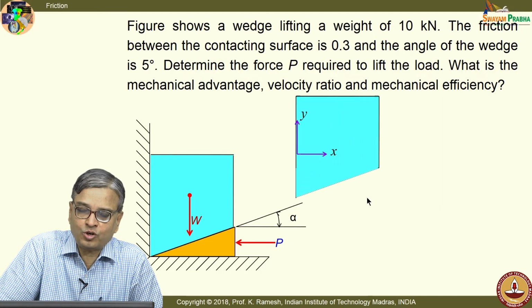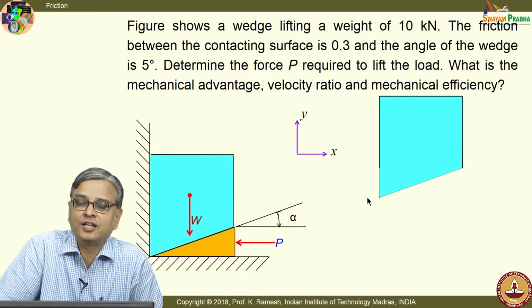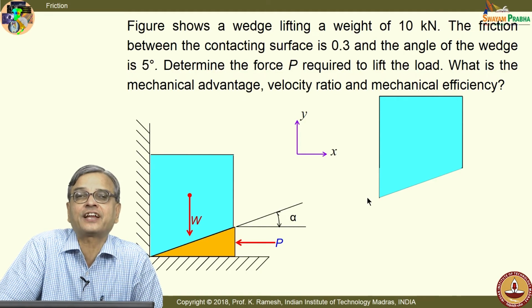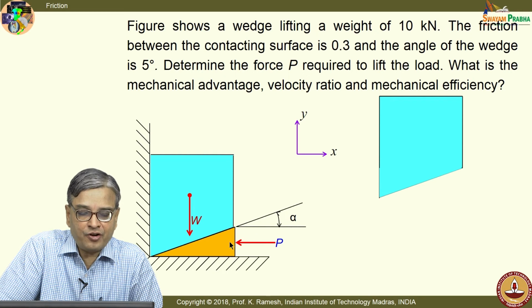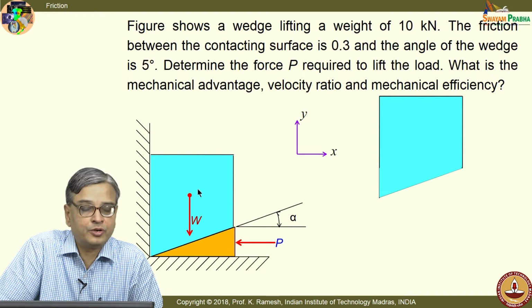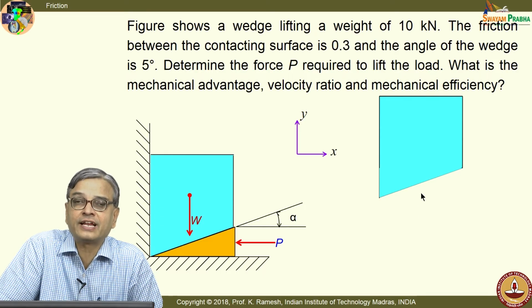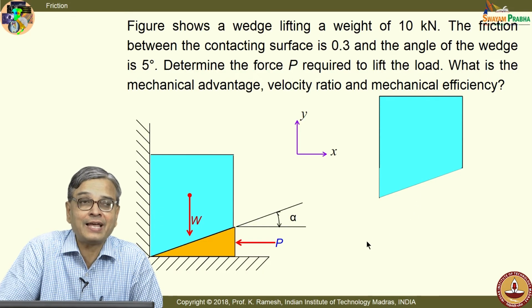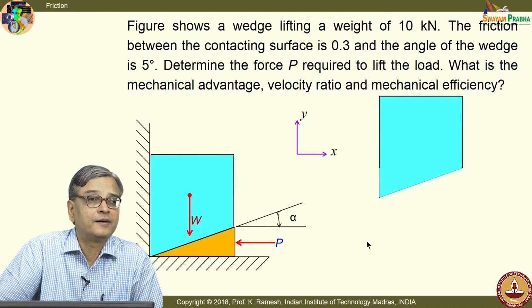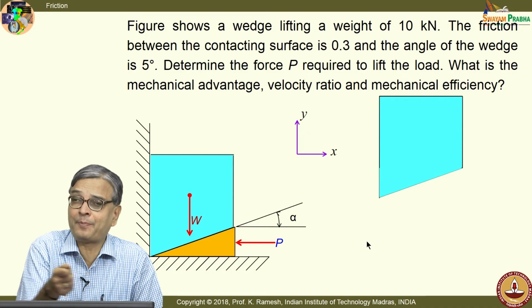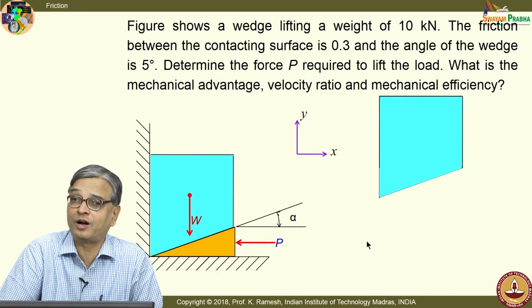And you will have to draw the free body, and in all problems dealing with friction, you have to indicate the frictional direction correctly. Here I am driving the wedge into the block W. So, what way should I indicate the frictional force? Because I am driving the wedge into it, you are deliberately applying a force in a particular direction. You have to recognize that.